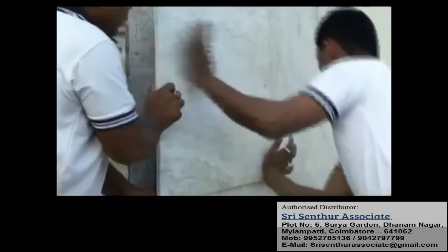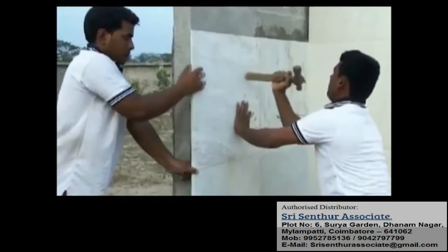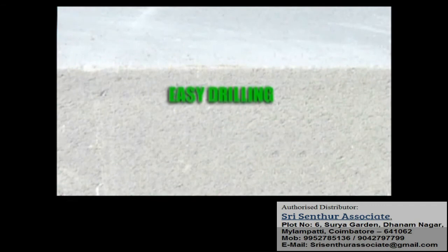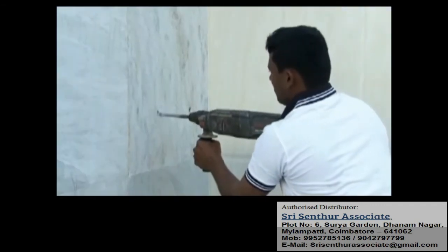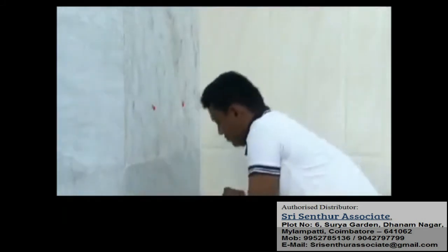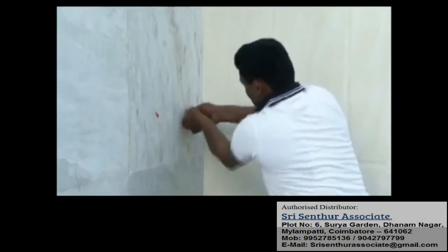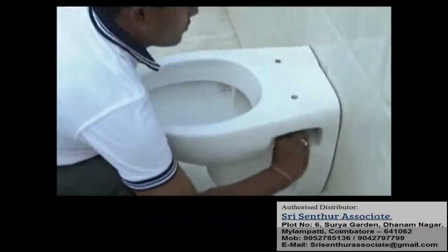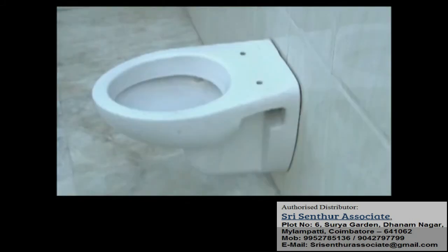Though lightweight, the walls made of AAC blocks are sturdy and can effortlessly support heavy marbles. Large tiles can easily be bonded to the wall. The AAC blocks can be effortlessly drilled by using normal drill machine to add various fixtures. After drilling, the holes can easily be blocked with roll plugs and fitted with the screws. A wash basin, commode and other fixtures can easily be hung.